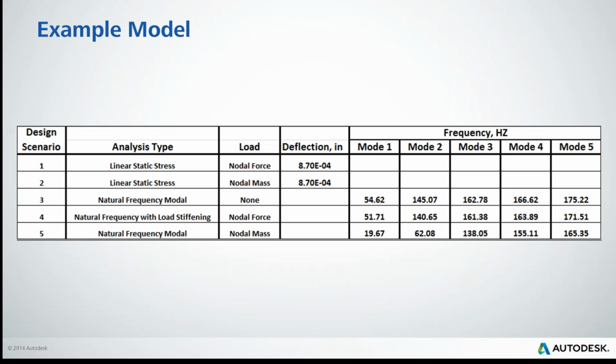We're not going to go through all possible combinations of why one would be easier than the other. Yeah, I think a good easy rule of thumb is that anytime you're getting into dynamics, you need to start considering mass, right? Whether it's vibration, like a natural frequency analysis, or seismic type events, mass is very important there too. And into nonlinear, right? Nonlinear static doesn't really matter, but nonlinear dynamics, like a mechanical event simulation or MES analysis, mass means a lot there, right?